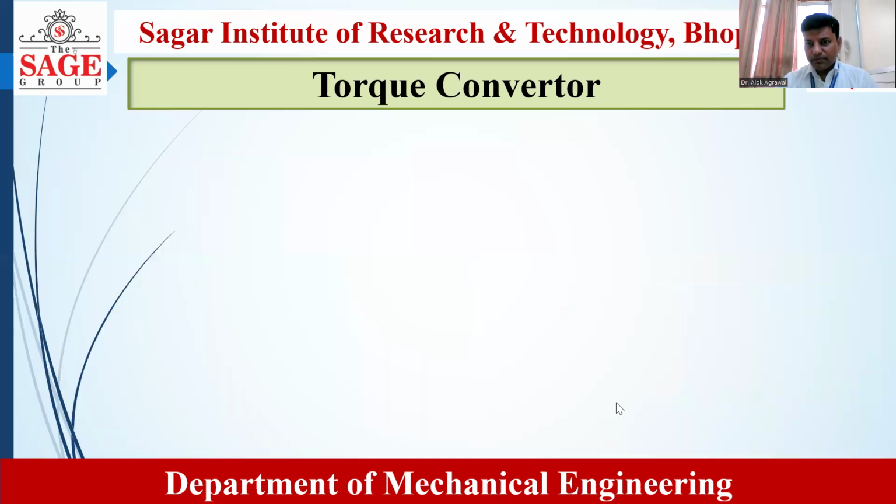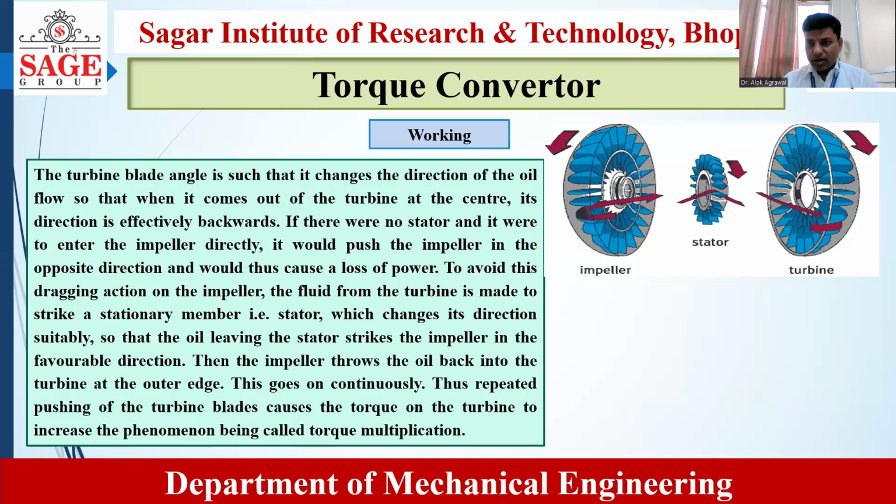Now what is happening here? After the oil strikes the outer edge, the turbine blades are designed so that the oil comes out from the center and tries to travel towards the impeller.